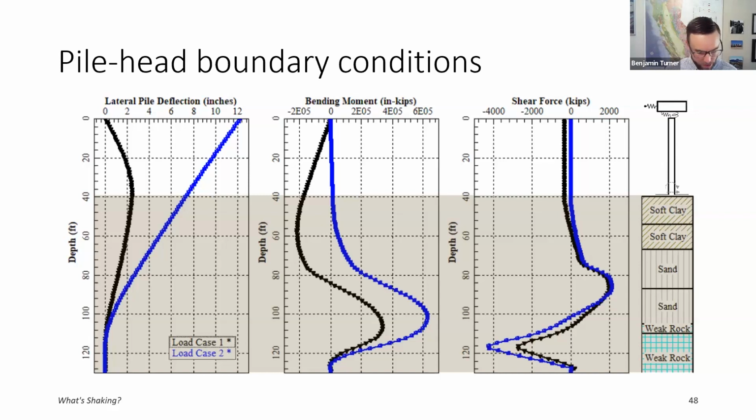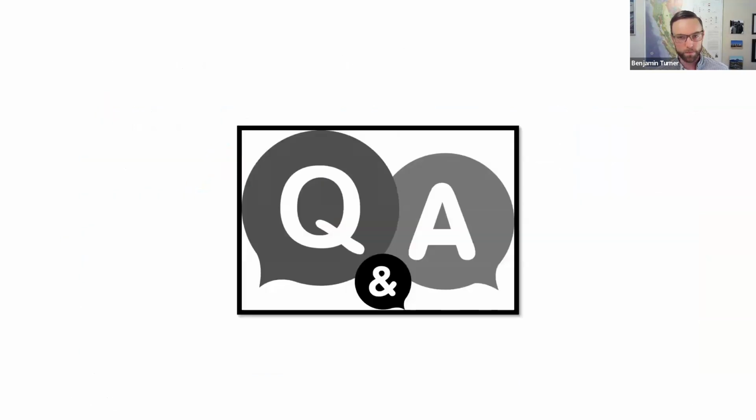But to kind of tie this all back together, the key premise here is that the amount of resistance that a structural element can offer in the context of a limit equilibrium slope stability analysis for the seismic case is likely even less than what corresponds to the full flexural strength or shear strength of the pile element. The only way to find that out is to do a separate laterally loaded pile analysis.